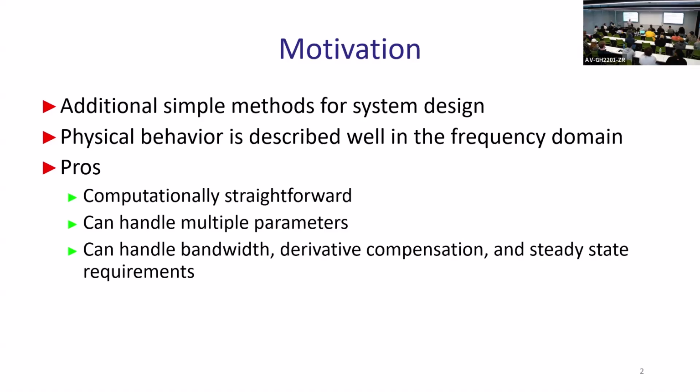So the idea is the system becomes faster. Transient response is much faster because you can handle higher frequencies. You can push your system to work at higher frequencies. And what are higher frequencies? It's just faster. This is what higher frequency means. Instead of that kind of slow oscillation, you get that kind of oscillation. So your system can move faster if it is a mechanical system, right? It can respond faster if it is an electrical system of some kind. Just faster, okay? So settling time is shorter, typically with higher bandwidth, but more noisy, and this is a big disadvantage.